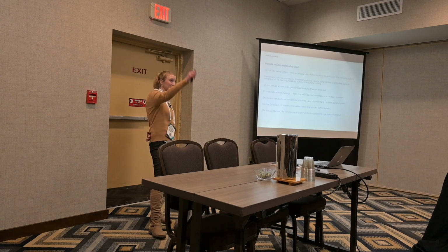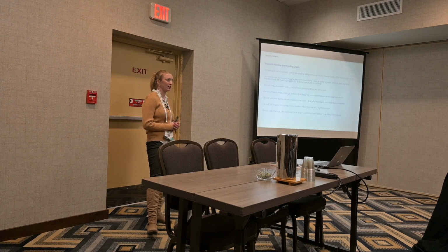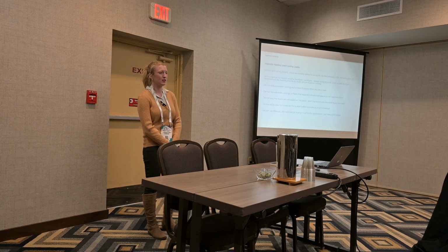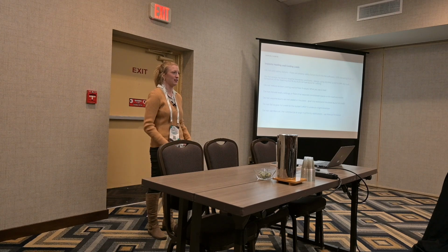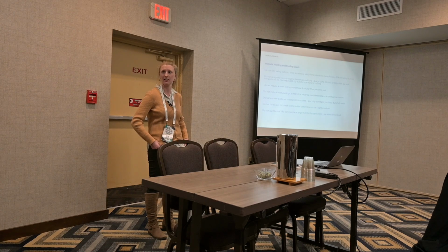Actually, I helped make this heat pump water heater guide for the Energy Star Next Gen new construction program. In there, I don't remember the number off the top of my head, but there is a number that gives you an estimate of how much BTU output it's going to give. So take a look at that number, and that should help. But if there's going to be a heat pump water heater, you want to consider that in your load calculations.